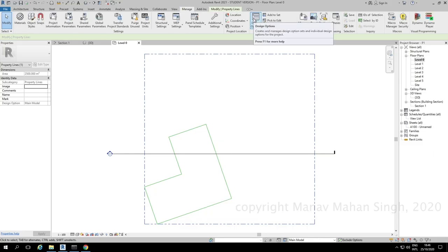Now, let's move to the Analyze option. First, we need to see how to model a design option in Revit. The model means only the mass model of the building. Other numerical design parameters we will see later. We may be creating multiple options. So, let's use the Revit feature to manage all design options.